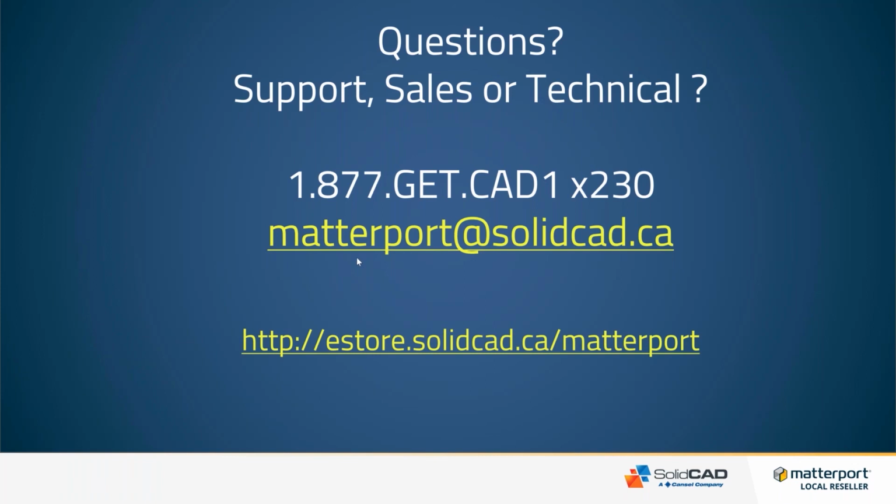Another question here: can you use a hybrid of the Matterport Pro 2 with the regular 360 cameras? What is the impact on the point cloud? Well, the 360 cameras will not provide you with any point cloud data collection, so you won't see any of the information from your 360 camera. Honestly, I think it's a bit redundant if you're using the Pro 2 and the regular 360s together. I would just stick to the Matterport Pro 2. You're going to get the point cloud data, and you're still going to get higher visual information. The resolution will be substantially better than the 360 camera. So try to avoid using the 360 and Pro 2 together if you can.